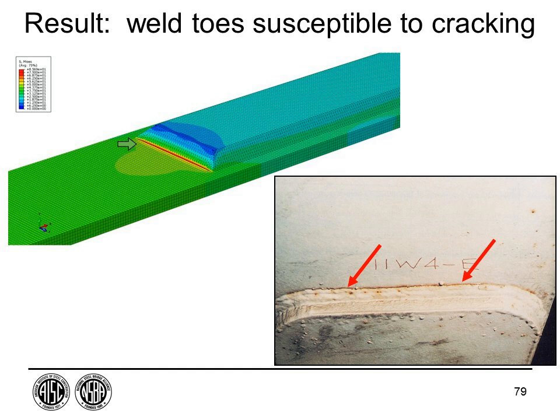And the other thing, for Paris law to work, you need an initial crack size. Fracture mechanics, that's what that's based on, has to have an initial crack size. And if you've run those numbers, I assume the person has, you can find that the life you get is incredibly sensitive to the initial crack size. So you just need to make some good assumptions and use good engineering practices if you want to use that. But we do that all the time.